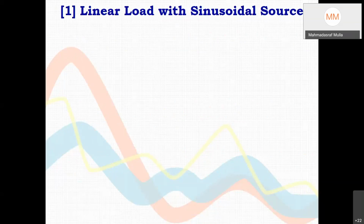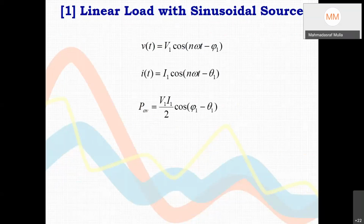Now briefly different case, like majority time we have sine voltage and we are having linear load. Capacitor, some combination, so RLC some combination. So it will just create phase displacement between voltage and current. So if you write power, power will come V1 I1 by 2 cos of angle between voltage and current. And V1 by root 2 is RMS voltage, I1 by root 2 is RMS current.